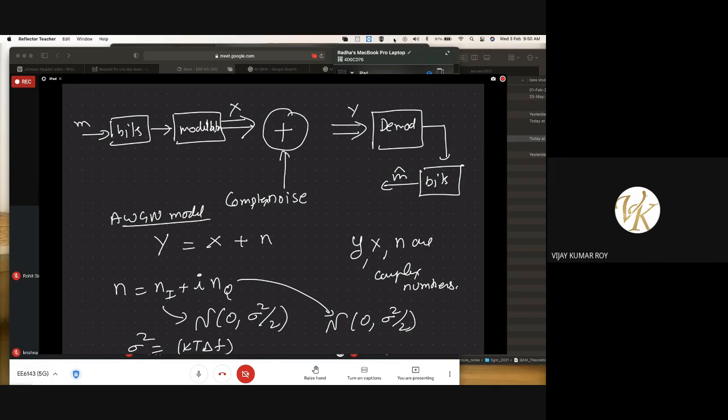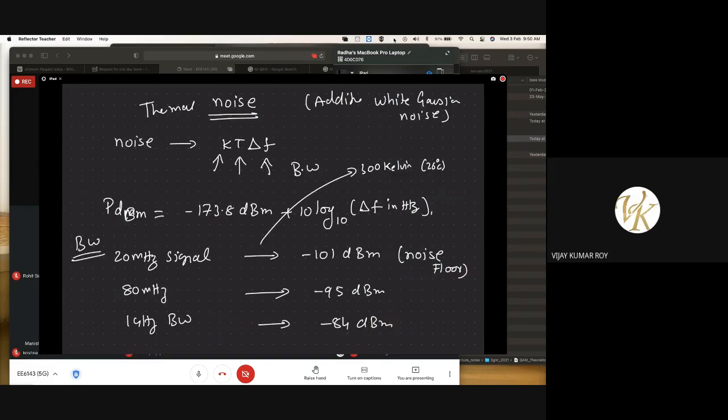This is VK Roy, Professor. Good morning. Good morning, sir. This question is related to the measurement aspects of the noise. Whenever we increase the resolution bandwidth of a measuring instrument for any signal, the noise floor, the white noise, increases automatically in proportion with the bandwidth, I think. Yes, that's the kT delta F. I was thinking about the measurement of EMF, where the noise floor always increases when we increase the resolution bandwidth. Yes, that's because of this delta F. That's what happens.